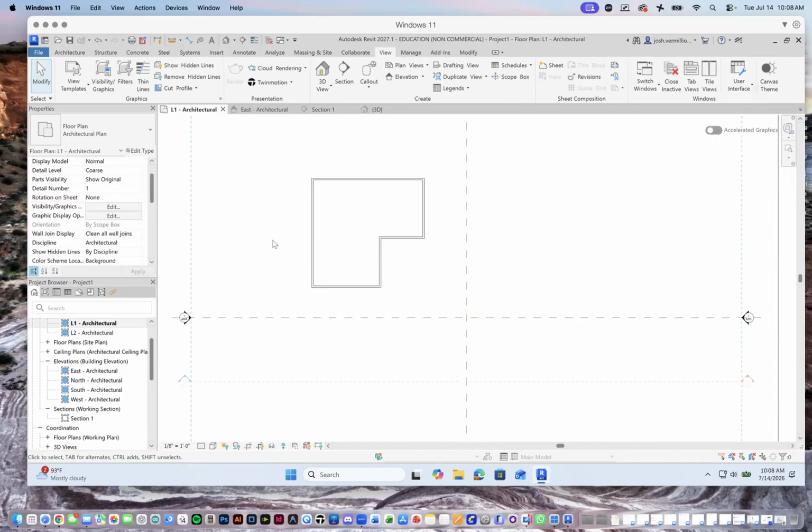constraints. And then what you can see here in this view tab is that we can always cut sections through things. We can always create more 3D views. As you start to add windows and doors, this will automatically start to create schedules showing each door and each door type, each window type, each room tag, each door tag, etc. So again, it's mainly a database that helps to automate and reduce redundancy and error when you're trying to put together the drawing set and describe your design intent in a set of drawings that can be handed to a builder, to a general contractor.